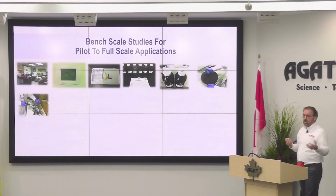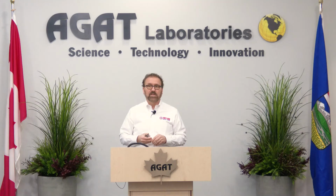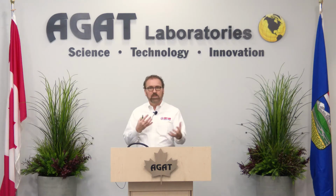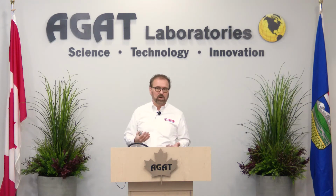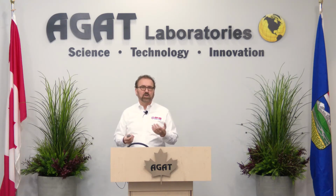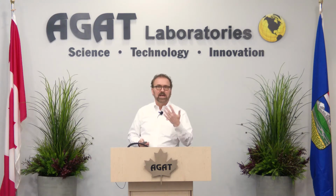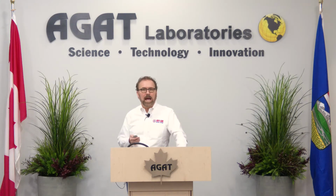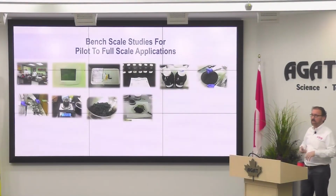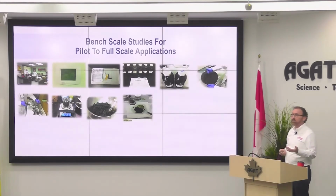If, for example, it's soils, we'll take their soils. In this case, there's a person mixing it physically, several kilograms of soil in a 9-liter stainless steel bowl, so it's well broken up, there's no clumping. We have it exposed. And then we can put that amongst all the jars of soil that we're going to be using during testing. We know the weight of every single individual jar, and by indirect measurement, we can determine how much soil we have in there, and then we can actually do the analysis to determine what absolute mass removal we achieved. All the testing in this case, because it was a Superfund site, was done in triplicate, not single tests, which are still effective, but this one required triplicate testing.